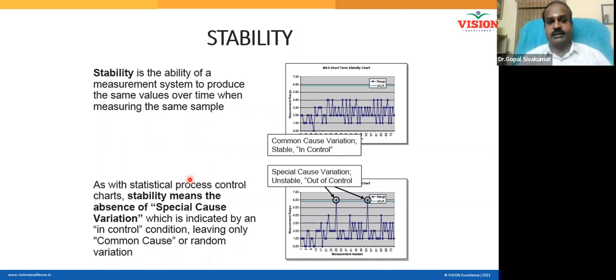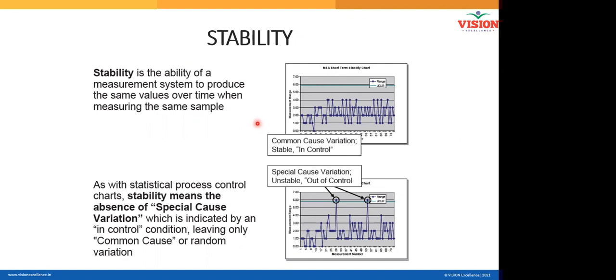You have a metrology lab where you keep your equipment like the dial gauge and other things. It is very important your gauges are maintained in good condition to give you stable readings. Suppose during the project, somebody drops your dial gauge, what will happen to your readings the next day? The readings will become biased. Am I right? Yes or no? If somebody drops your gauge onto the floor, can you use it for the next day? No. It should be maintained, right?